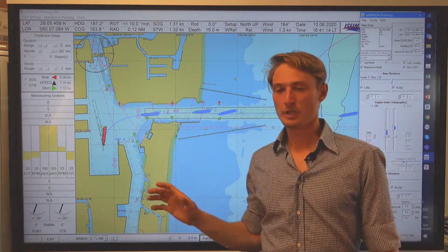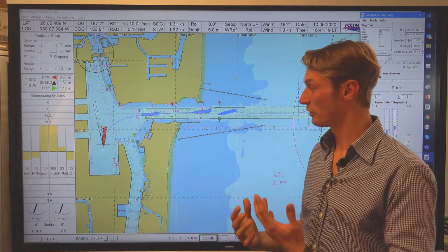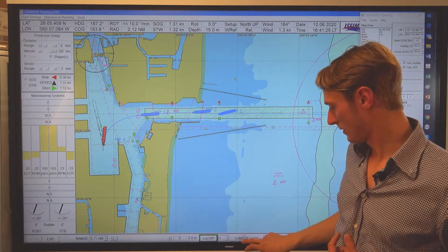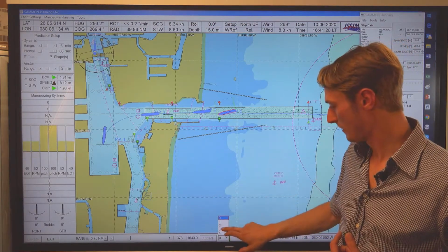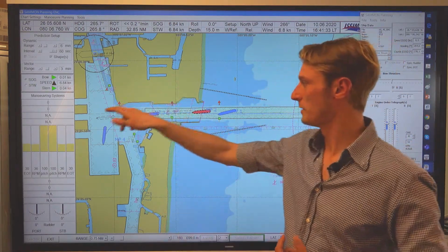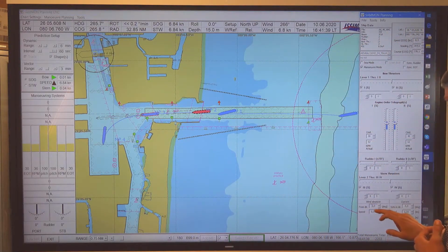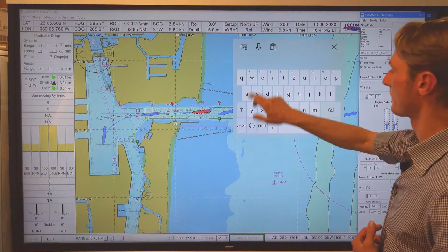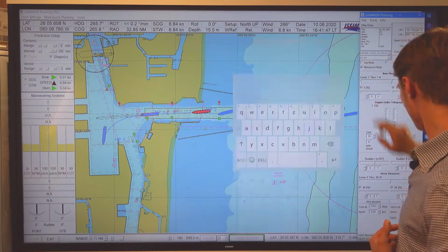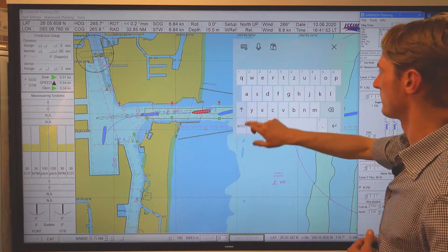Now, to keep it simple, we just had current in this maneuver, no wind, to point this effect out in a stronger way. Let's imagine that in this position, I can jump back to maneuver point 3, we would have wind suddenly gusting up, and let's say we have a wind from west. So wind is coming from 270 degrees, and we give it a speed of, let's say, 20 knots.